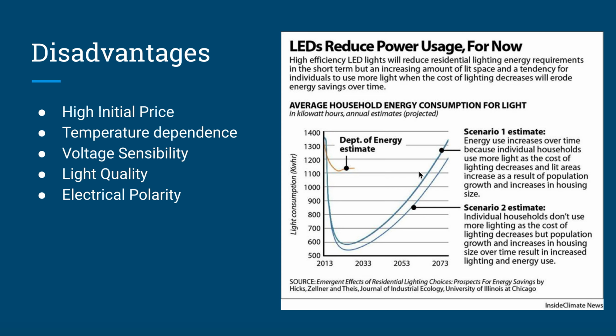LEDs must be supplied with a voltage above a threshold and a current below the rating. Current and lifetime change greatly, even with a small change in applied voltage and light quantity. Most cool white LEDs have a spectra that differ significantly from a black body radiator like the sun or an incandescent light. Electrical polarity. Unlike incandescent light bulbs, which illuminate regardless of electrical polarity, LEDs will only light with the correct electrical polarity. To automatically match source polarity to the LED devices, rectifiers can be used.